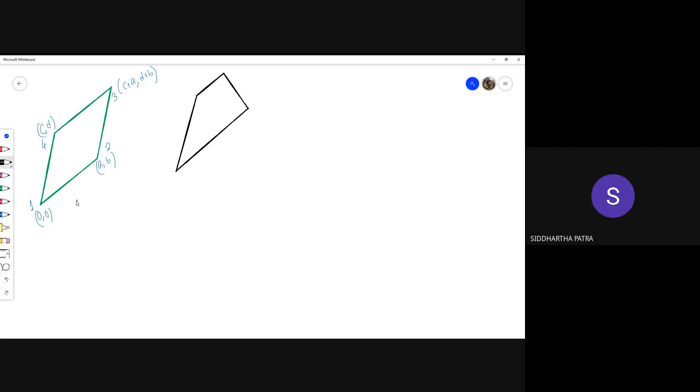Let's take this example. If I take coordinates to be like this, and just for the sake of simplicity, I have taken one of the nodes to be at the origin. Even if not, it doesn't matter, because ultimately you are subtracting coordinates of one node from the other in every term in the Jacobian. I don't know what the expression is, but in every term you are essentially doing that. Because essentially the Jacobian represents, in some way, the area.